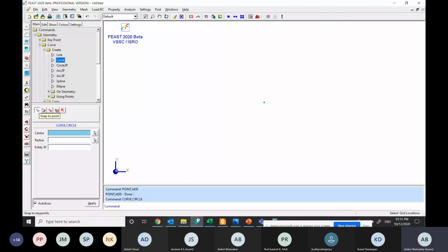P stands for point, that is the geometric point. N for node, that is finite element nodes. And then here we have snap to corner option, where you can snap it to vertex, point, node, and so on. And this is snap off option, which can snap anywhere onto the screen. So since we have dimensions and we have one point which is created at the origin, I'll use this point filter.